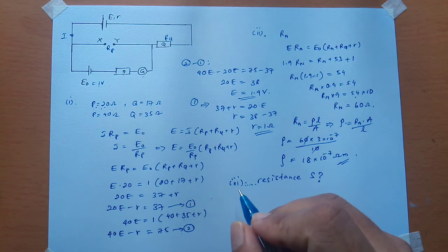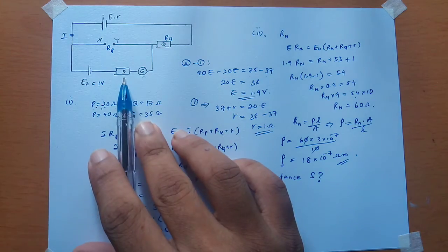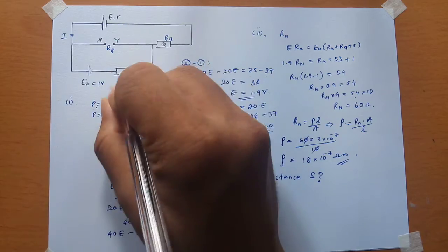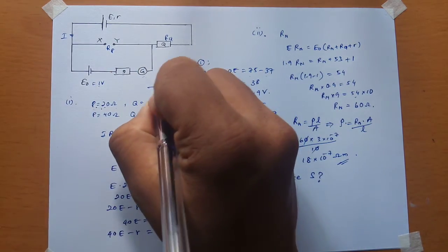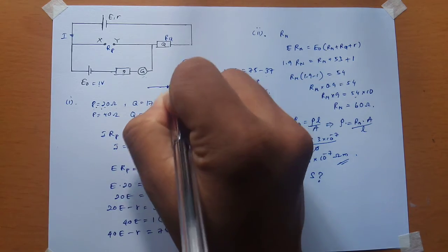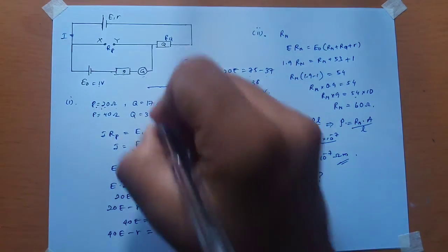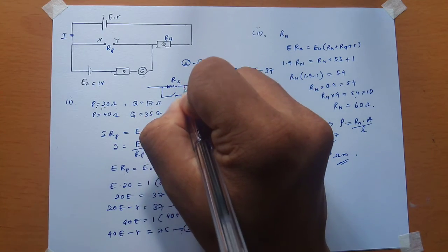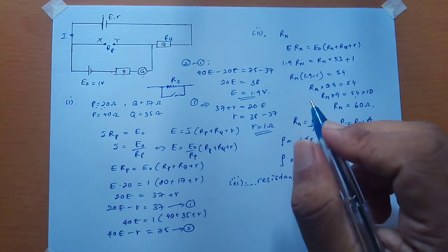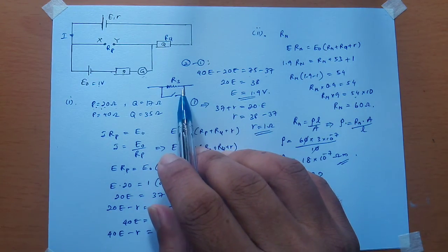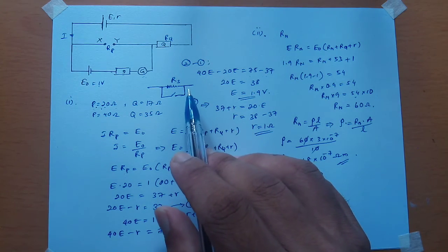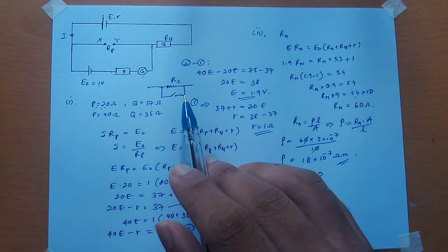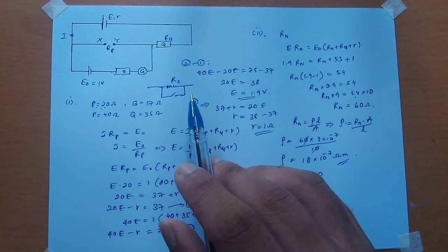And then also they ask what apparatus is used for S. For the S, what we have to use here is a large resistor, safety RS, and then we put a switch here to short the resistor once we are done. I will explain in the next question, because they ask how do you use S in order to find the balance condition, zero deflection, accurately.